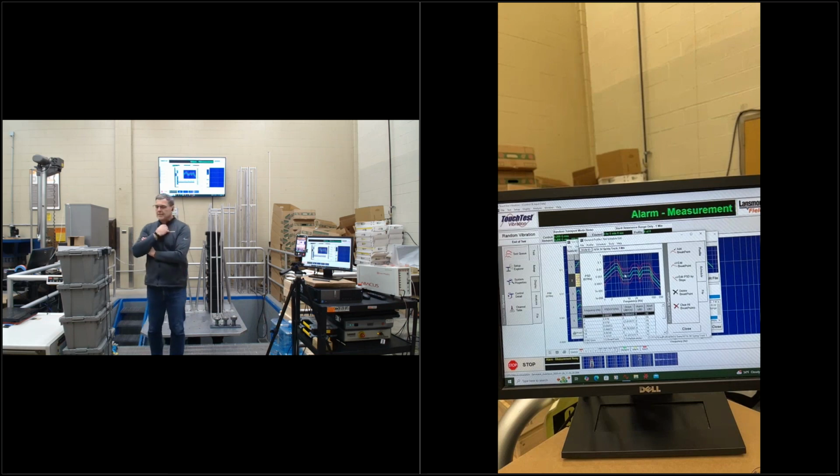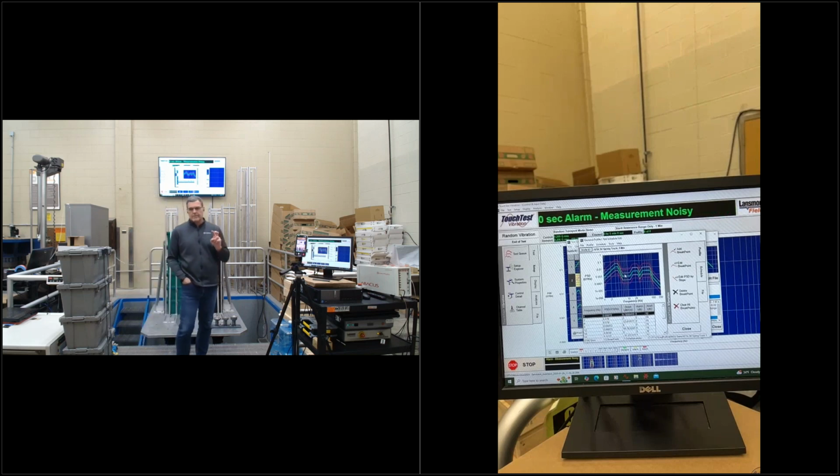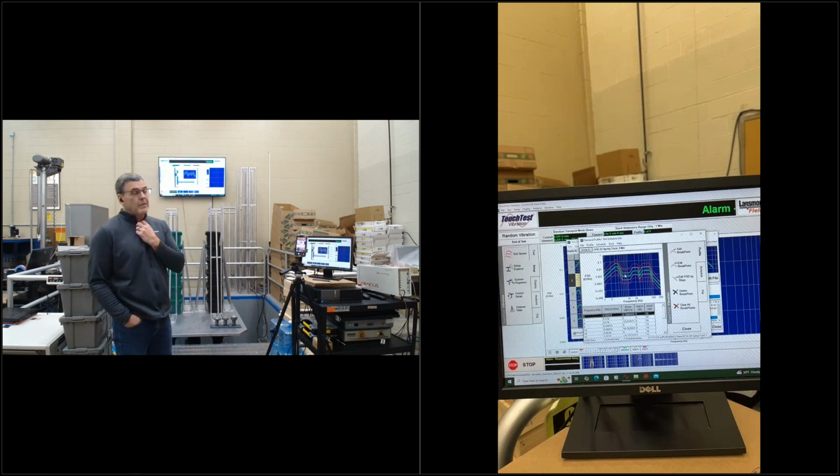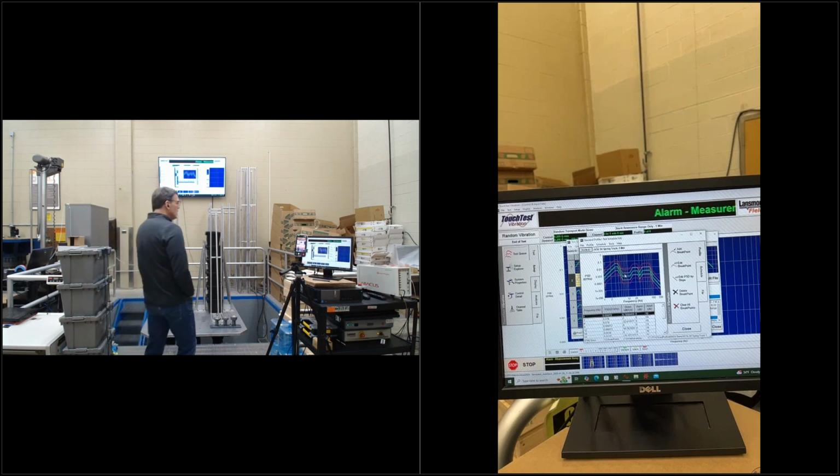If you can pass the test and you have a history of using it, and you can say, if it passes this, I have proven that I have no problems in the real world, more power to you. But it's not a simulation of anything. It's hard to connect the dots on that. Even ISTA still recognizes it in some of their lower level 1 series tests, which are non-simulation tests, but it's not included at all in something like general simulation, 3 series or higher tests, because again, you can't connect the dots. So you do have to spend more money if you want that higher level of sophistication. But if you want to simulate and get closer to reality, that's what you've got to do.